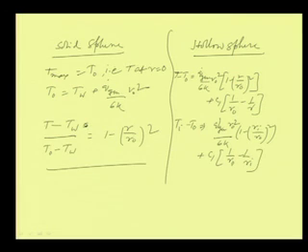Now, from this equation we can find out the value of C1, because T_i, T naught, r_i, r naught all are known. If you know the value of q dot gen, we can find out C1, and if we put this C1 here, we can get the expression of temperature. So, this way we can find out the temperature profile when there is heat generation also in case of hollow sphere. Okay. Now, we will discuss a few problems in this.